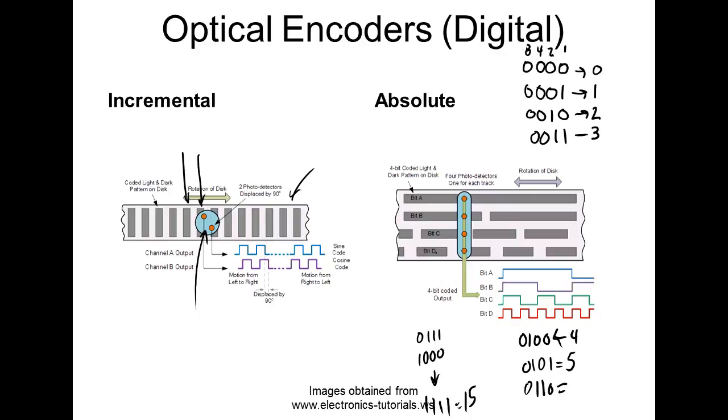The incremental encoder, basically the way it works, and they're actually showing the sensors. These are usually optical sensors. Down below the bands, they will have a light transmitter, and up above it, they'll have a light receiver. As these bands move, they either let the light pass through or block the light, and each one of those patterns would be equal to a position.